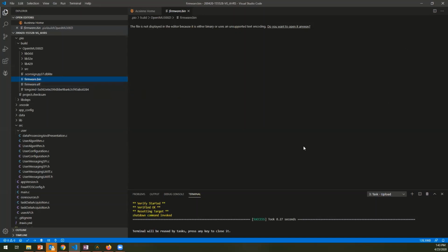One thing to note, if you are using the ST-tools to write a binary application directly to the part, you should check the start address that you use. So you don't want to overwrite the bootloader and configuration data. So this information is in our documentation. That's the OpenIMU.readthedocs.io.